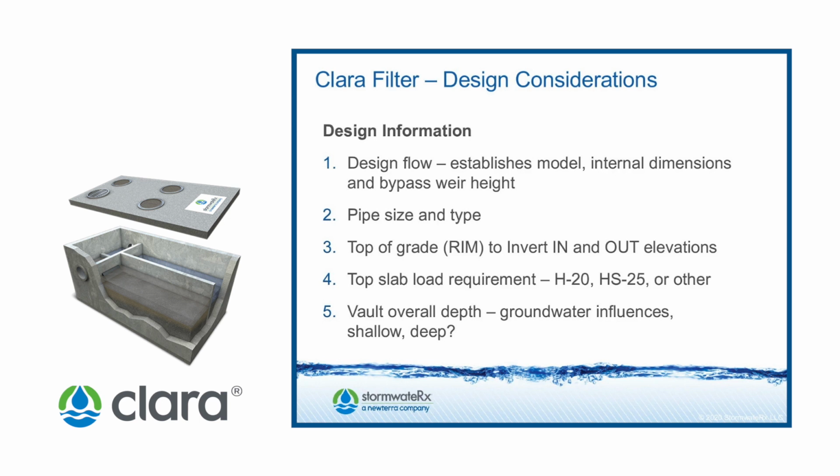Total top slab load requirements or traffic rating would be required if the Clara filter will experience being driven over. So it'll be clear that it might be an HS20 or an HS25 type loading. Could be even higher for some of the port locations. Finally, we had asked if the site experiences any groundwater influences. If so, buoyancy collars may be needed to establish proper vault footing.